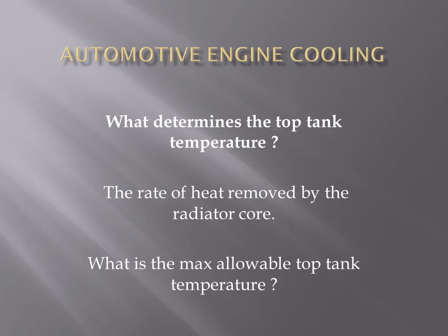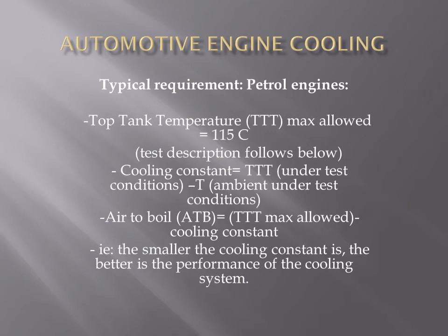What is the maximum allowable top tank temperature then? Typical requirements for petrol engines: top tank temperature, max allowed, is usually about 115 degrees centigrade.